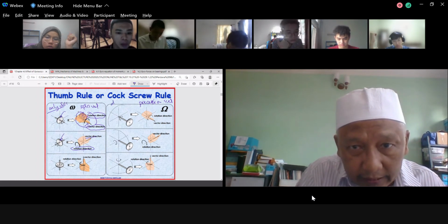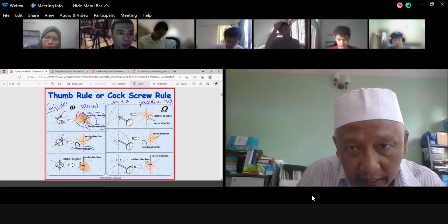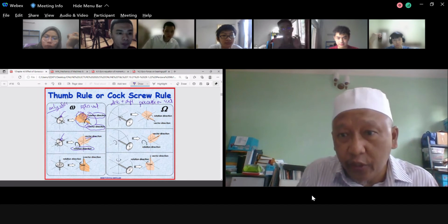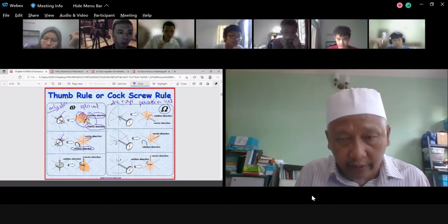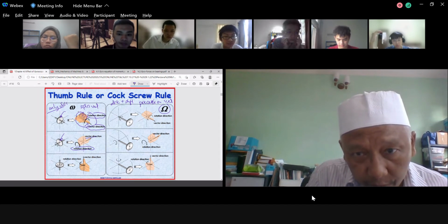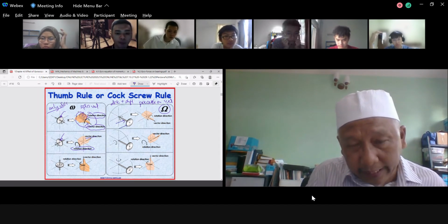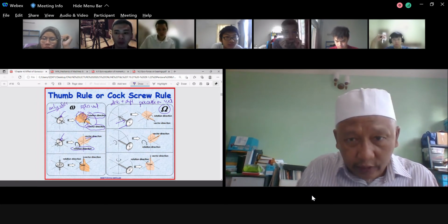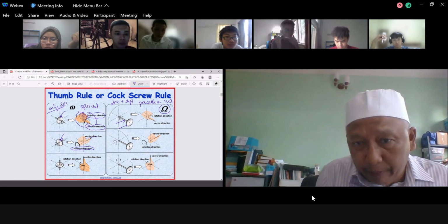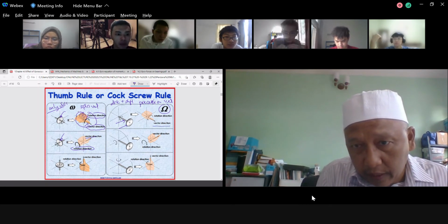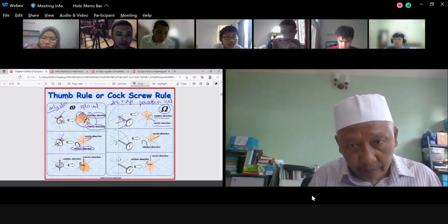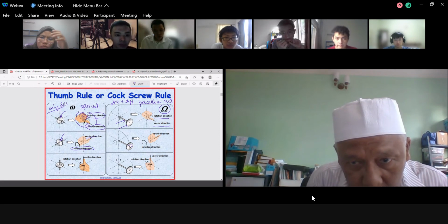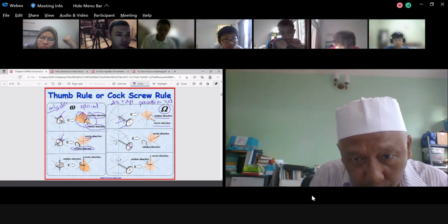Now this is plus the shaft, the whole structure carrying this. Two different things, right? Even though we also call it omega, we call this one the precession velocity. So it simply means that the shaft rotates, and this one also rotates. In this case, the shaft is rotating in the same direction as this, so both are pointing in the same manner: direction of a vector, and direction of rotation. But in the other case, this one is rotating here, but at the same time the whole structure will be rotating that way.